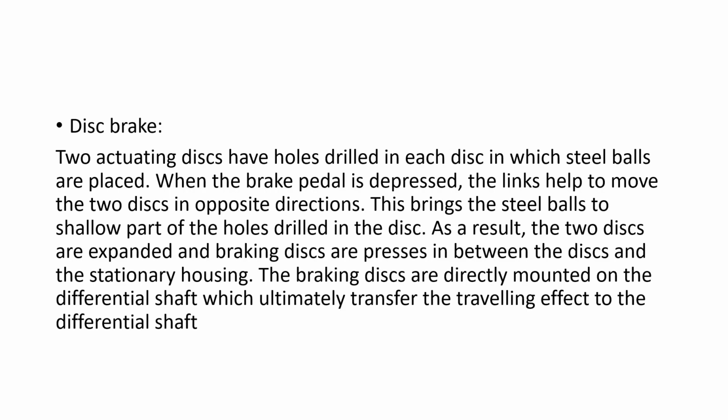The next one is the disc brake. You can see this in the B275 models. It has double disc type mechanical brakes, mounted on the differential hubs. This type is self-energizing, so the natural movement of the various parts is used to increase the braking action once it is started by the foot pedal.